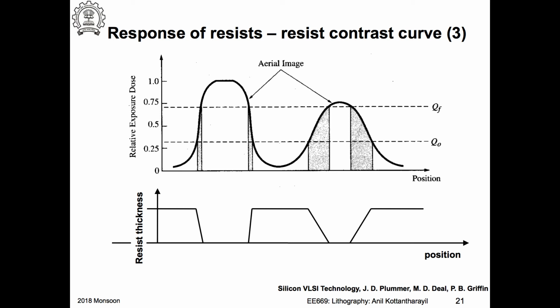Of course, there is another technique called backscattered electron, meaning the same system but a different type of detector is used for this. But the secondary electron microscopy is the most frequent thing, because backscattered does not give you good resolution, okay, but it is good for certain other things.